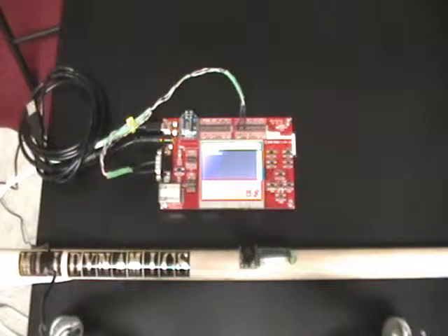In this view, you see the ultrasound mounted on the walking stick. But there's one more sensory device, the accelerometer, that is already embedded on the device kit. And why do we use the accelerometer? The accelerometer is used to validate or give more precise RSSI values coming off the zigbee unit. At different configurations, RSSI values change, and for the localization algorithm, this is required to home in on the precise value of location that the algorithm would predict.